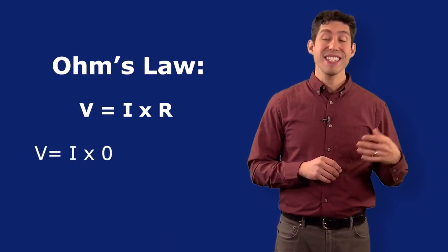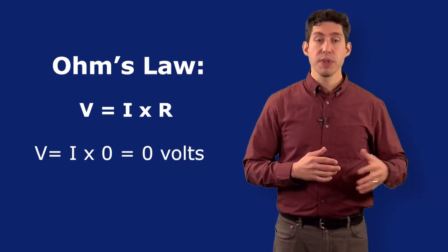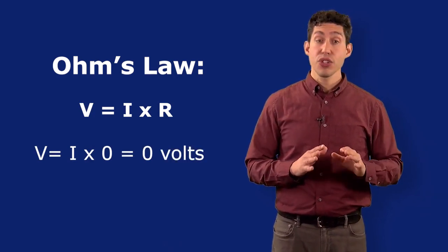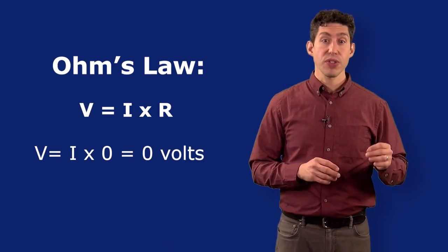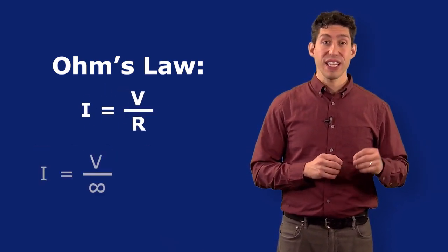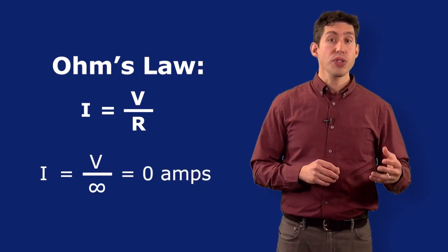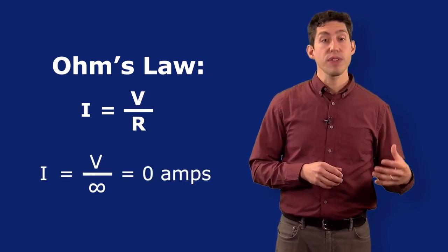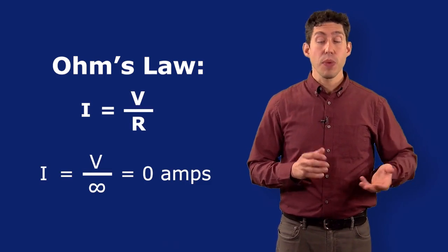Mathematically, when the resistance is 0, the voltage must also be 0. This is because there's no potential difference between the electrical signal and ground. Likewise, when the resistance is infinitely large, the current is also 0 because no electrons can flow through the circuit. This matches what we observe in reality as well. This IV curve is used to help us evaluate individual solar cell performance using a term called fill factor.